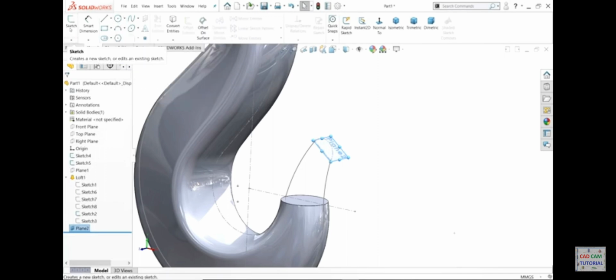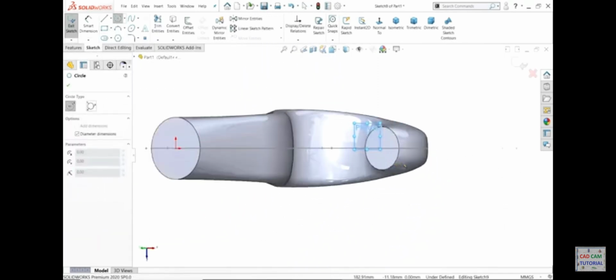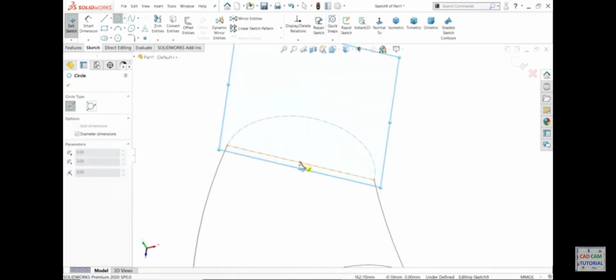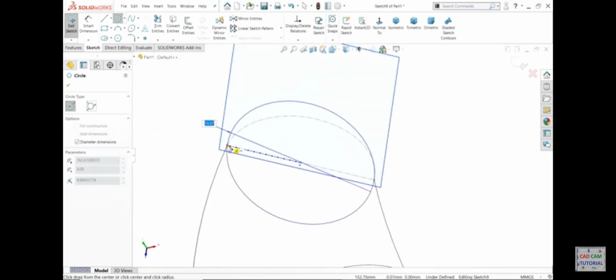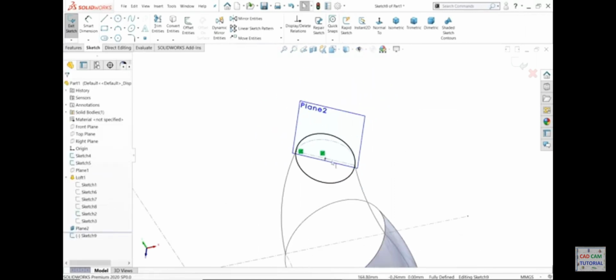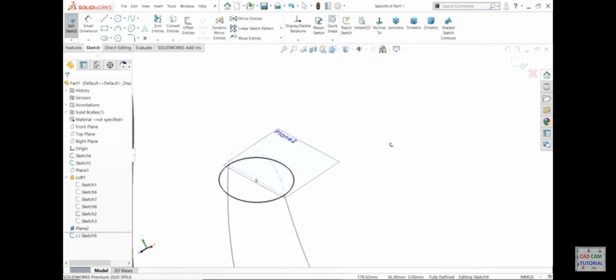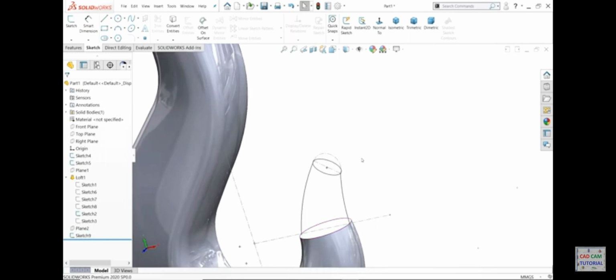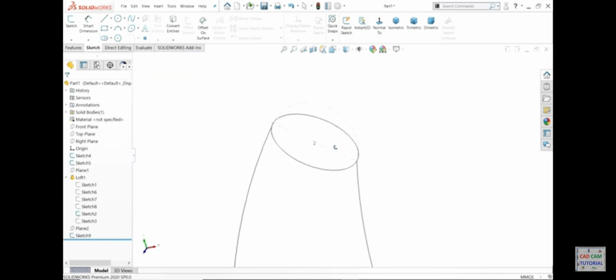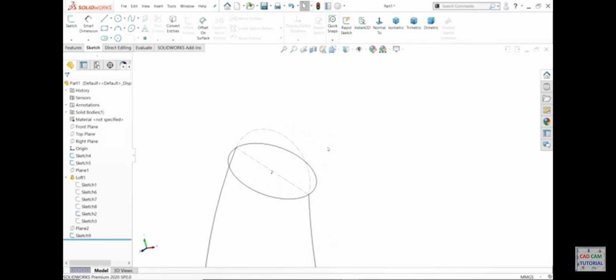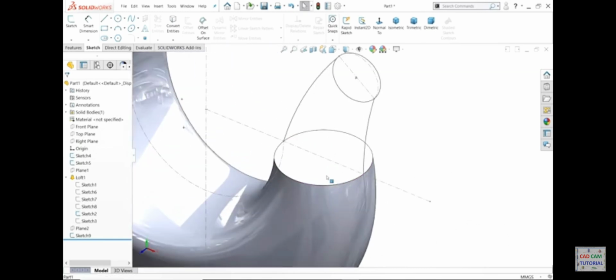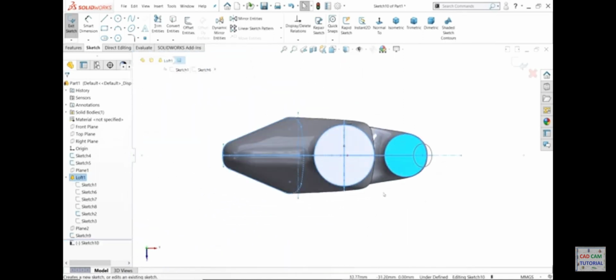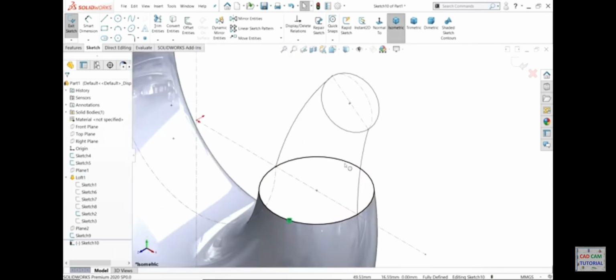Activate, first select sketch, activate circle. Now here we have to draw a circle. Now see, end to end we created. Exit. Now click and hide. Now again here also we need a profile, so sketch, click convert entities, so that this circle is created, say OK.